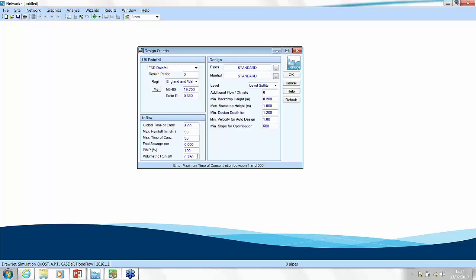Well, what it's saying is at the moment, by default, 75% times the 1.3 is then multiplied by the rainfall landing on just the impermeable area. So we get about 100% runoff from impermeable areas and nothing from permeable areas. So any rainfall landing on grass verges, back gardens, that sort of thing, will not provide any contribution under this assumption.